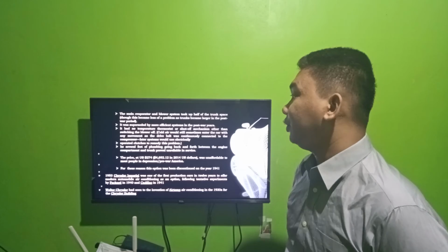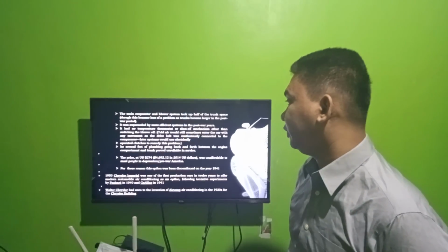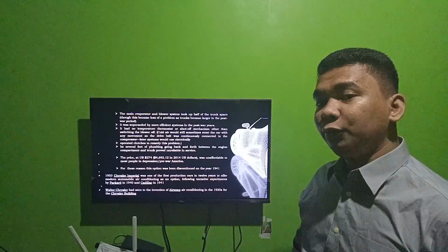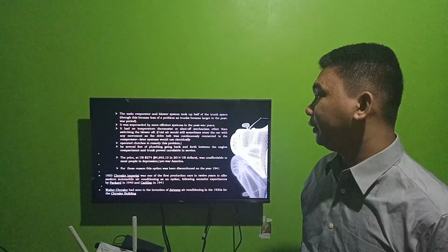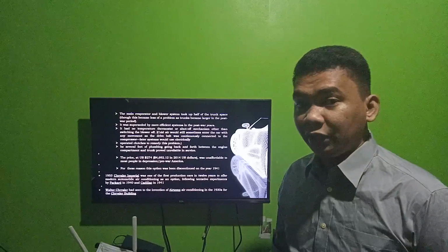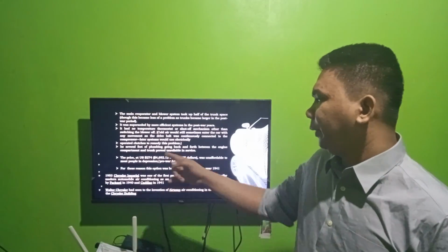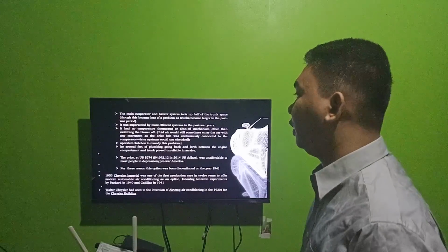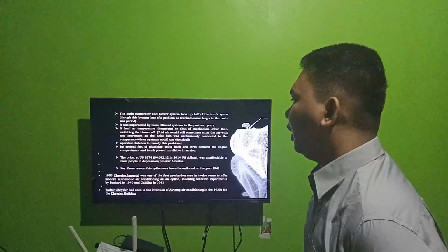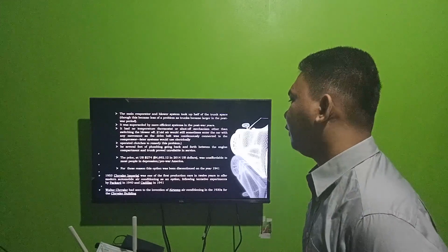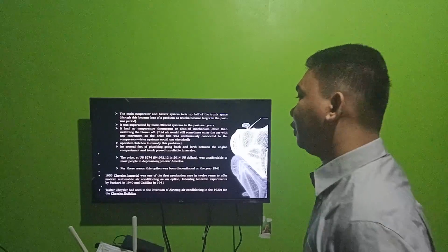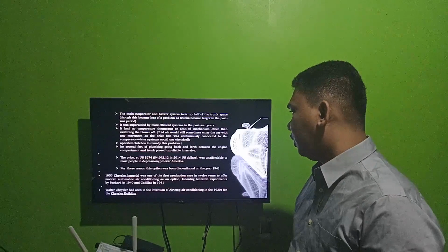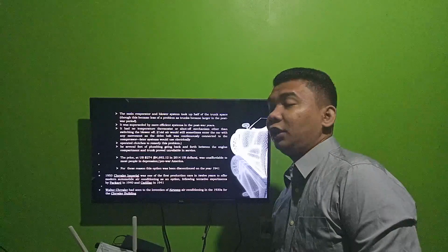It had no thermostat or shut-off mechanism other than switching the blower off. In those first designs there was no switching mechanism, so there was no thermostat or shut-off when it got too cold. An overrunning clutch was added to remedy this problem, but the compressor was continuously connected. The refrigerant lines going back and forth between the engine compartment and the trunk proved unreliable in service.